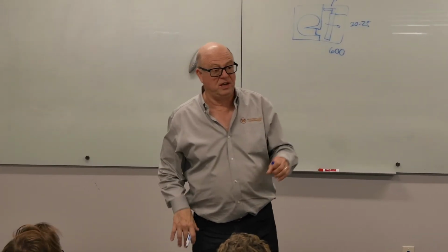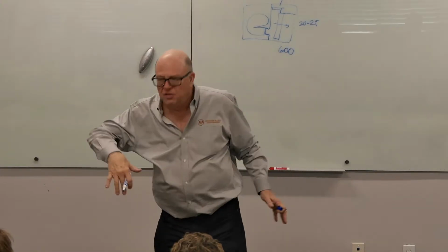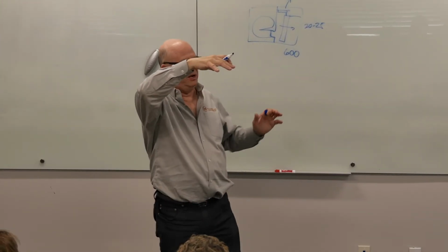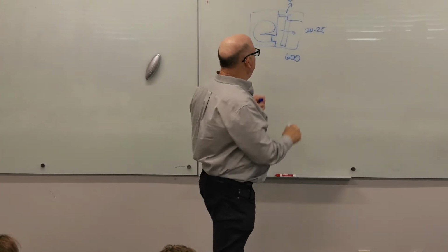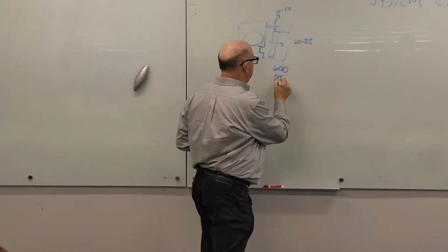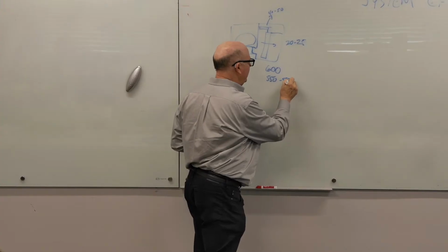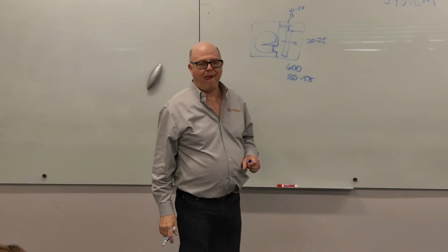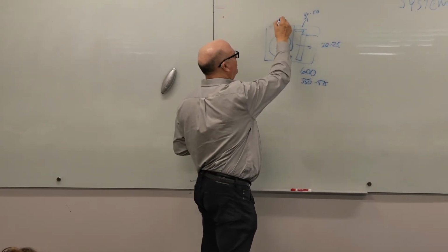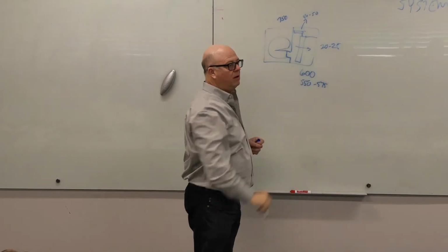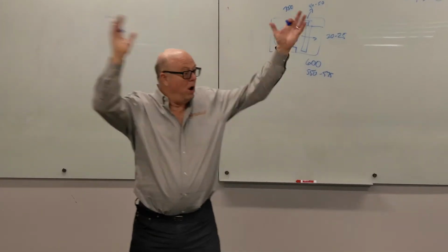You can do that on a VAV unit based on the idea that it'll very seldom ever be at maximum airflow, okay? Most people will tell you that the max is probably 550 to 575 feet per minute. The recommended maximum on a heating coil, depending on the manufacturer, is usually about 750. Because there's no water to blow off.